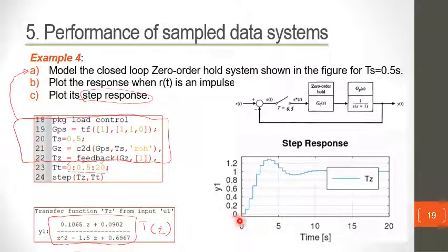So this would be your output y(t). It comes in this nice and smooth format of an approximately analog continuous time signal. And you will see from the step response that there's a peak overshoot, there's a bit of damping here. In fact, you can tell that in this particular instance, you have a conjugate pole pair here. These poles must be a conjugate pole pair. You can tell by just looking at this graph.